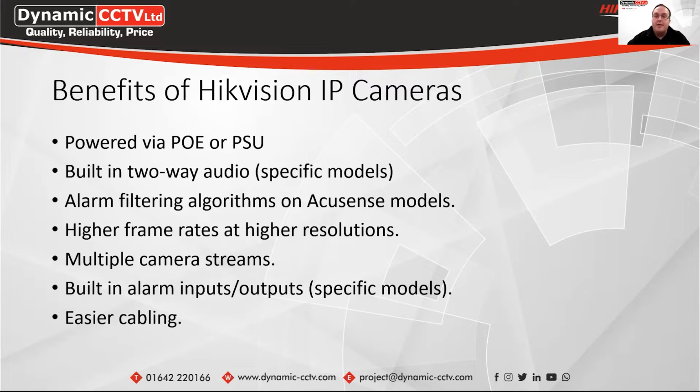Some of the larger cameras still require a PSU, but a lot of them now are using the newer BT PoE, and that would allow you to get up to 90 watts of PoE for the power draw, so you're not having to use a PSU for the cameras for general use. There are still a couple that do require PSUs, but predominantly now most of the Hikvision range is available to power via PoE, which means it's a lot simpler on installation.